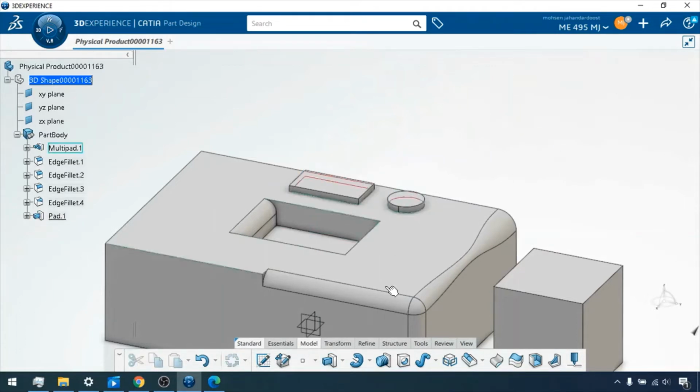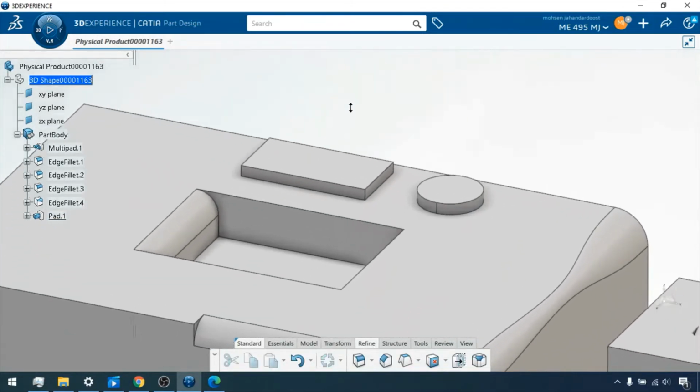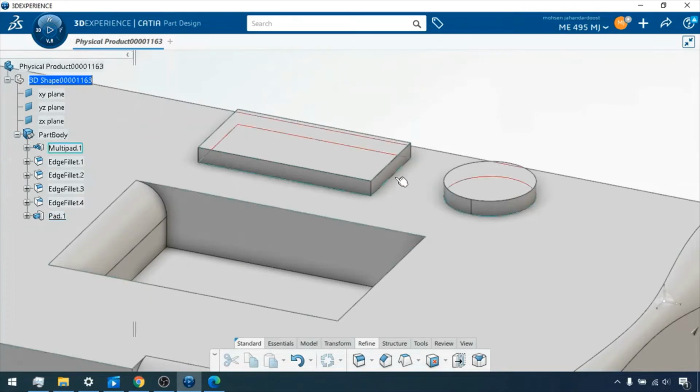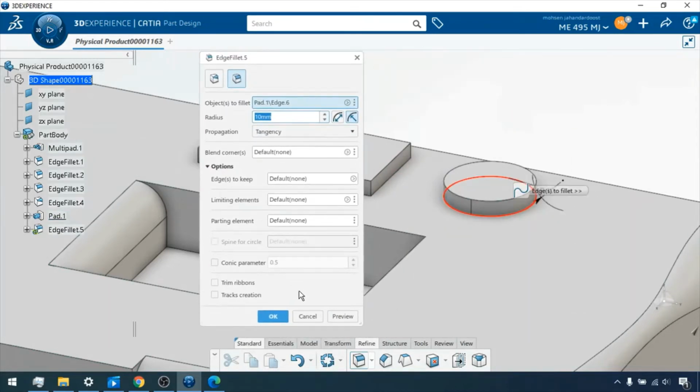Okay. The next thing is that sometimes when your edge is very small, when your shape is very small, and you create the fillet in some location, there is a chance that it changes the top faces. So for example, here if I create the fillet for this edge that I have on the bottom part, right now you can see that it's green. This is red. It means that it cannot create the arc or the fillet with that value, the value of 10. So when I create this fillet, sometimes it changes the line, the face, the profile that I have in the top.